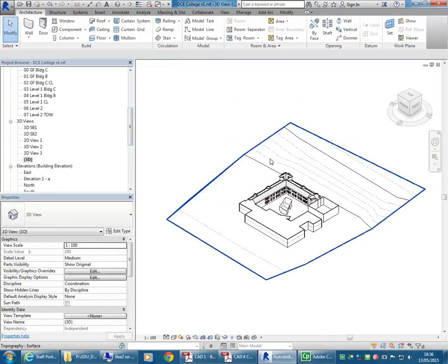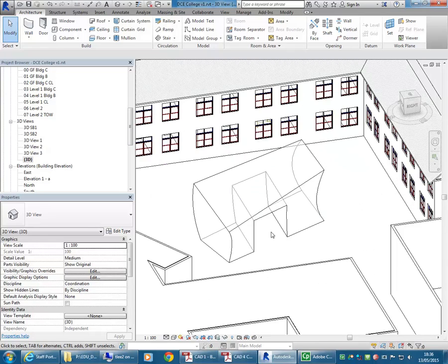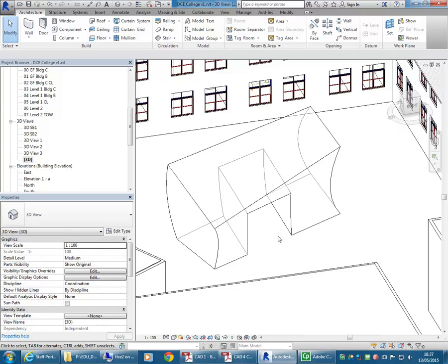Right, so again, just to show you what massing is really intended for, it's not really meant as a detailed modelling tool. So if you're thinking about making complex furniture and other things like that, it's probably not the tool to use. And unfortunately, Revit isn't either. So you can do some things with Revit. Fairly standard geometry is not a problem. But if you need to make complex geometry, neither of those programs are really the right one. You'd probably want to use either AutoCAD if you want to do accurate 3D modelling, and you can model virtually anything that's buildable using AutoCAD. Or the other option is a full-blown 3D package like 3ds Max, which again you can use to model anything. Yeah, I tried to use it before for a project where I was using geometric on the wall.